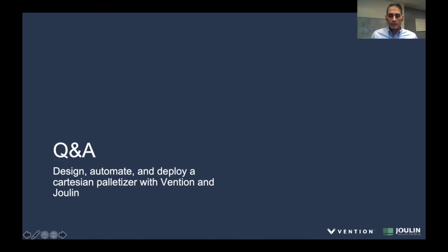So this is going to be dependent on the project, obviously, and what you're picking and what your motion profiles are. But generally, in most situations, for a 40-hour work week, we're going to see approximately 2 to 3 months of foam life. But there are situations where we see 6, 8, 12 months of foam life, and it all comes down to how you're utilizing the foam gripper and how you're compressing the foam. So typically it's going to be about 2 or 3 months for a 40-hour work week.